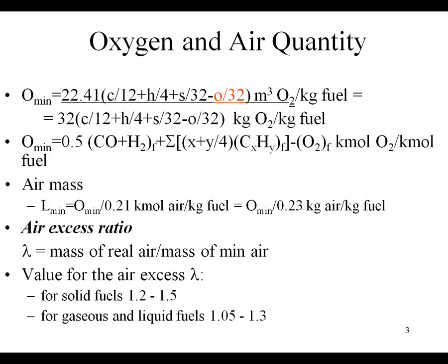Perhaps you will come here for a doctoral thesis or master thesis, and then we can learn about how to avoid the formation of pollutants, because the nitrogen from the air, when the temperatures are over 1000 degrees Celsius, is turned into NO, meaning a high pollutant. And this pollutant is not originated in the nitrogen from the fuel. It is originated in the air, in the nitrogen from the air. So this air excess ratio must be taken under control.